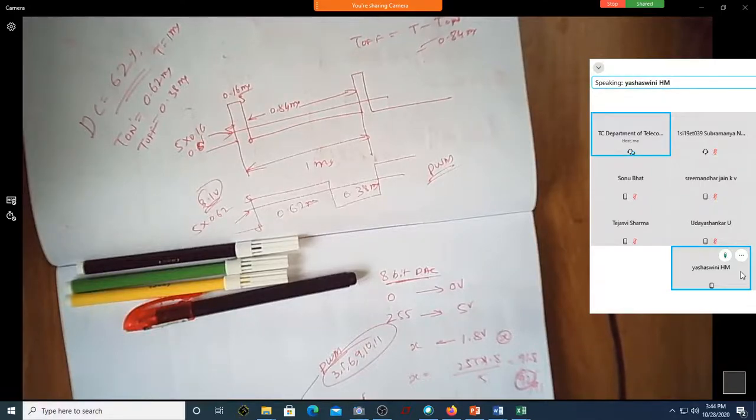Meaning whatever was executed prior to that will still hold. So the LED is on for 1 second, then it goes to the next line of the program, which makes the LED equal to 0, and that again holds for 1 second. Can you see now, 1 second on, 1 second off, in an infinite loop? Yes, sir. So that delay will make your program halt, so it will not proceed.